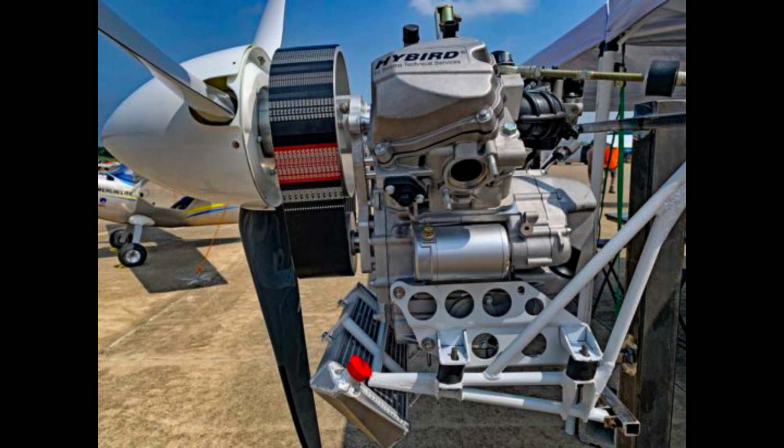A 4-stroke engine must also be warmed up. The 4-stroke engine has a pressurized oil system that provides more uniform engine temperatures to all of its components. Takeoff power can be applied as soon as the water, cylinder head temperature (CHT), oil temperatures, and oil pressure are within the manufacturer's recommended tolerances for takeoff power applications.